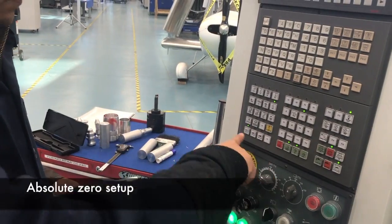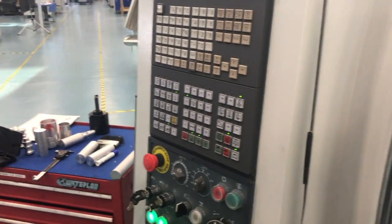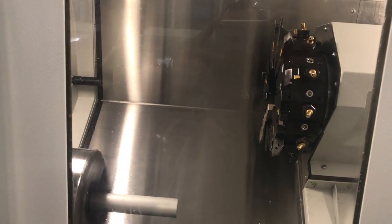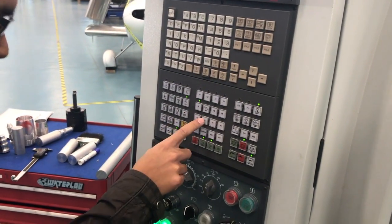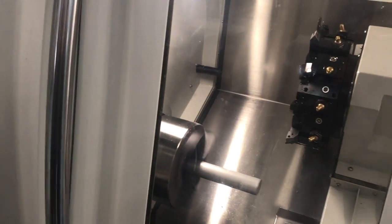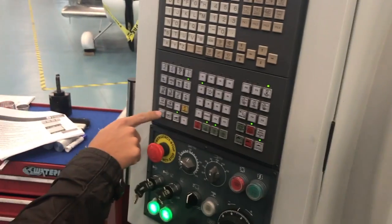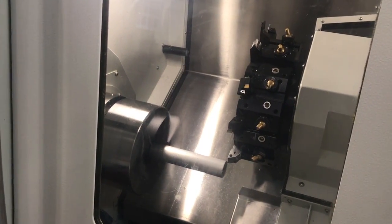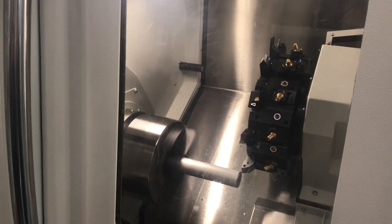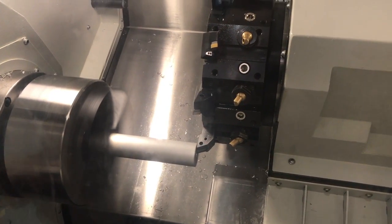And then it's time to move the turret in the Z direction, as we can appreciate. When we get very close, we change to the X value, and we move it again very close. It always needs to be done manually to avoid a collision. When it's very close, we proceed to turn on the spindle with the revolution that we set before, and we remove just a little quantity of raw material.